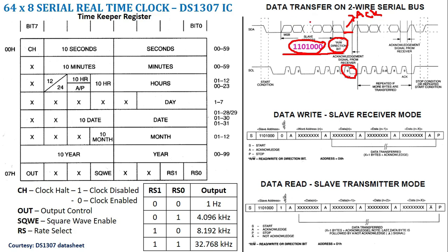If this 8-bit data is properly received, during the 9th clock pulse the receiver will try to make the SDA low. Then the transmitter will understand that the data has been received by the slave, or that the data has been put by the slave into the bus. Then comes the data again. Once the address is sent, we can keep on sending the data, and the slave can also keep on putting data into the bus.